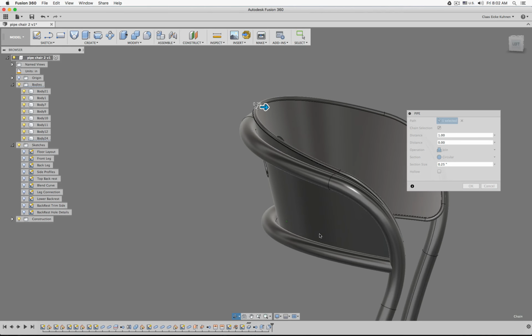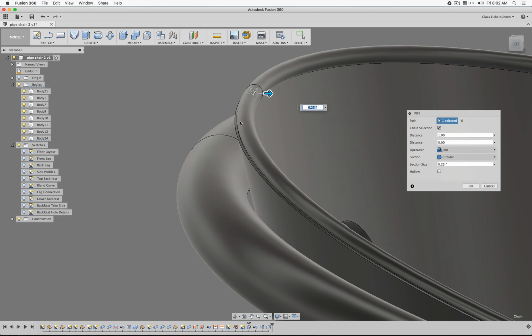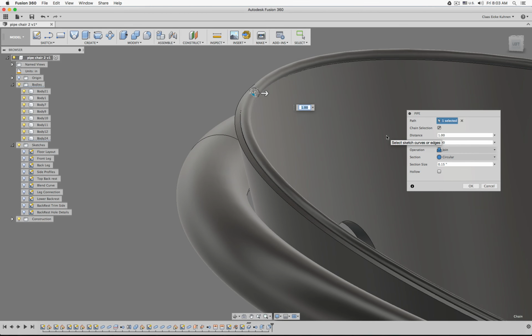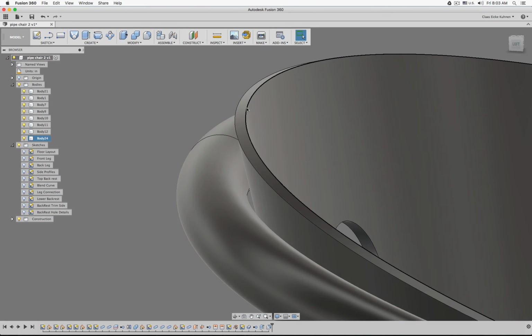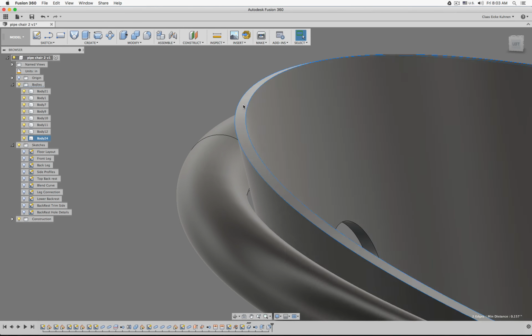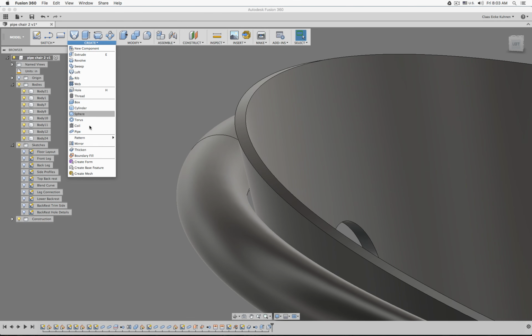And currently, you see my dimension is set so there is a small gap. So I could either try to be more precise, or be a little bit more specific and make this just so small it only runs on one side. Or, for example, I would have to measure the distance. So I click this and shift click this one. No, 2 lines. It tells me the distance. So 0.57 inches. So now I could go back, go to pipe,